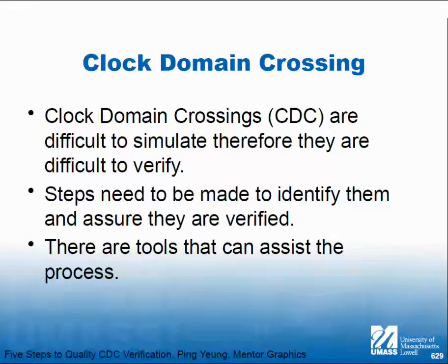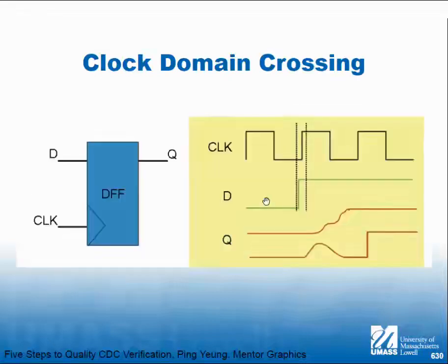Now, if we went into an analog simulator, we'd have a better time with this. Because remember, these digital signals don't go like this when they switch. They go like this, and maybe they even go like that. The analog simulator will show you that. But it would just take forever to do an analog simulation of a million gate design. Literally forever, right? Where forever is defined as the useful lifetime of the chip you're trying to build.